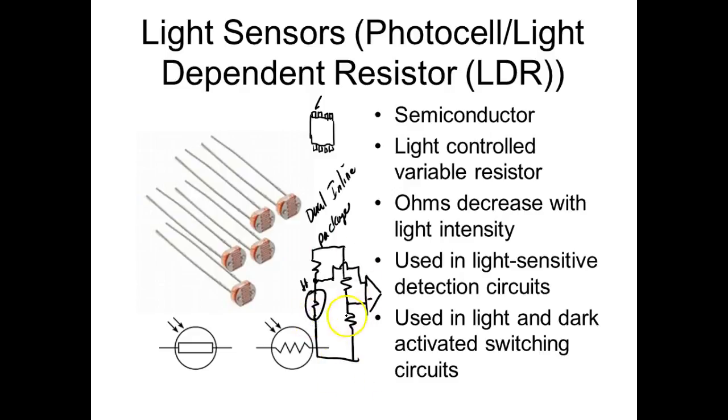And what happens is it switches condition. If this input is bigger than that one, then the output would either be a negative voltage or 0 volts, and as soon as the positive becomes bigger than this one, it would switch.